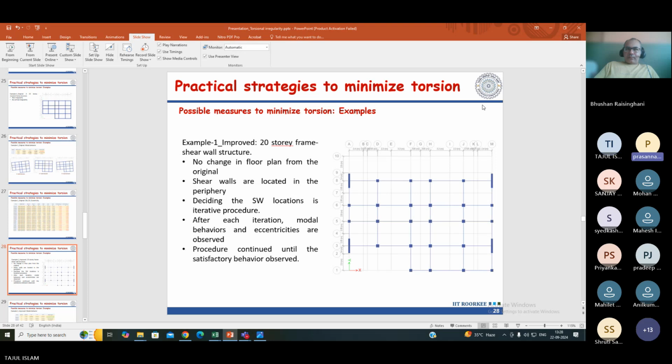It will be ignored simply because you are designing it for moments and shear, not for the torsion forces in the walls and columns. That is what you are calling a wrapping torsion. That wrapping torsion you have to consider as per the ACI code procedure, but the Indian code is silent on that one. Actually, I have to look at this, because the software will not take this torsion into account while designing the shear reinforcement for columns and walls.